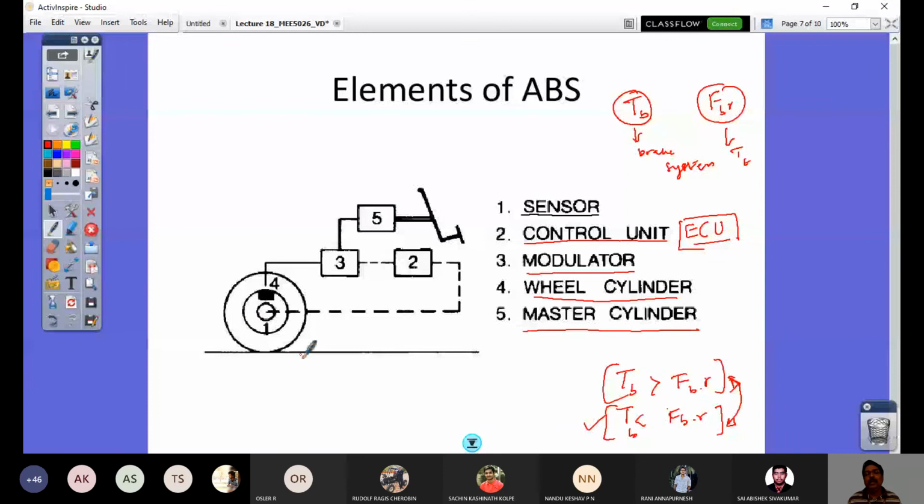We have done a quantitative assessment in the previous lectures, looking at the conditions of deceleration associated with front wheel locking, or with the rear wheel locking before the front wheel locks. Those conditions we have seen. They should be the same as what we have seen for the road, with that important assumption: mu is constant there. When it is not so, what will happen?